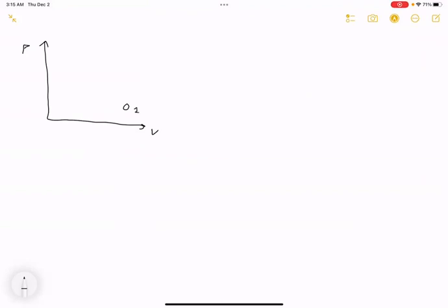We then reduce the specific volume a lot by compressing it, right? And this is, of course, the compression. So the piston is moving up and squeezing the fluid inside. And of course, the pressure goes up as the specific volume goes down. So this is sort of curved upwards and to the left. This we said is isentropic, or if you want to call it polytropic with n equals k, that's fine too.